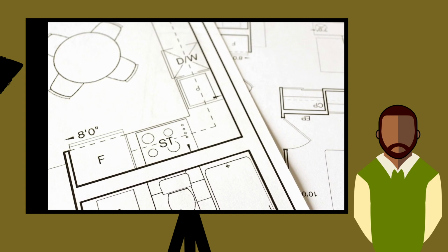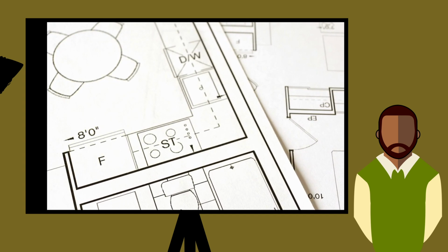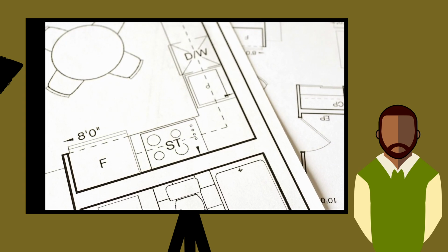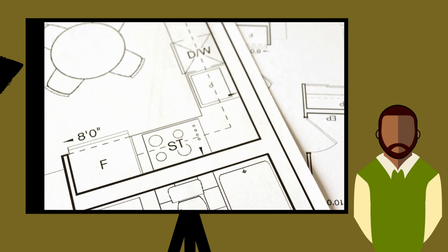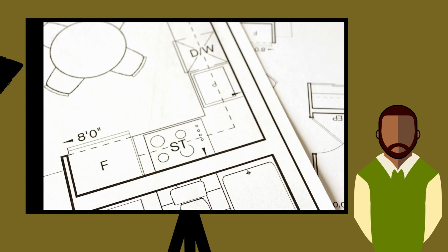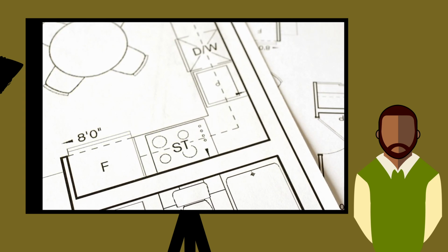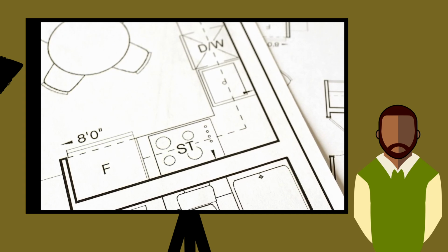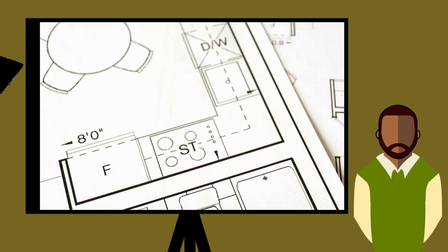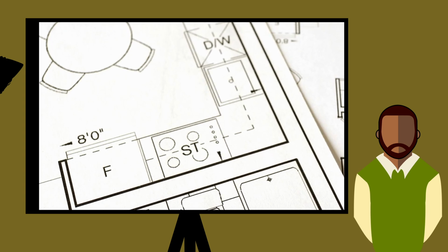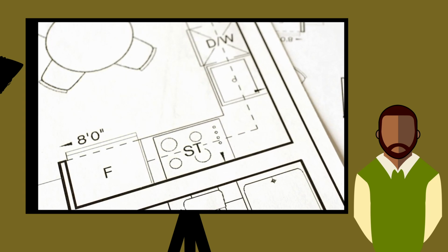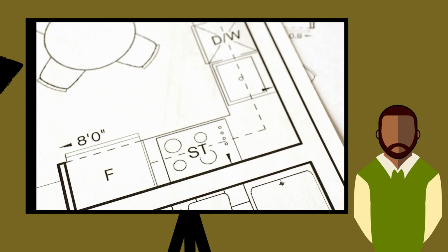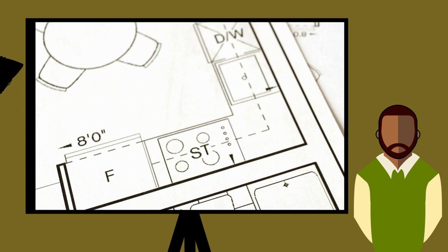And when it comes to ADUs in general, and for anybody wondering about handicap requirements in terms of the actual architecture required, you can expect things like wider hallway widths. Think about fitting the actual wheelchairs. You have to think about more space in the bathroom, how to make this place able to fit a wheelchair, but also things like grab bars in the bathroom.